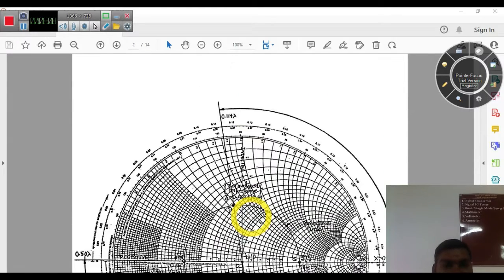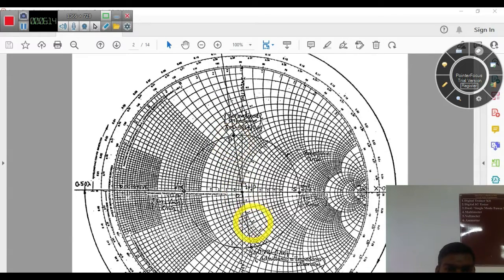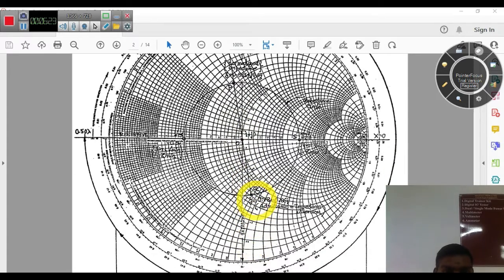Next, the second parameter is the asked load admittance value, right? So here we have the load impedance. You just have to draw an opposite line from this center. So starting from point P and through center O, you have to extend the line, so the opposite line is drawn. That line cuts the circle at this point. So here you have to mark the real part value, like this, and the imaginary part you mark like this here. So we can write 0.78 here. This value is approximately 0.78, and since the load is in the downside, we can write minus 0.86j, and this is the normalized value.